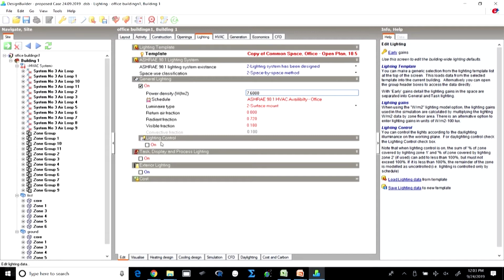and this photo sensor will sense the amount of light which is available outdoors. In a couple of previous lectures, while we were discussing the indoor environment quality, we were talking about the daylight factor DF, and there we were talking about the outdoor illuminance, the amount of light which is available outside. These photosensors will have a threshold limit, a cutoff limit.